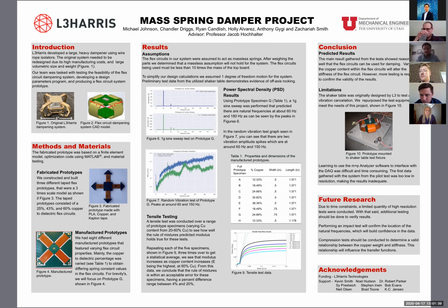And so we didn't want to take an iterative approach where we ordered and tested, because we figured that would take too much time. And so we used 1D and 2D models, FEA and Matlab code to develop and predict where a starting point would be in order to get a frequency under 2000 hertz dampening, such that we could get a project that they wanted.